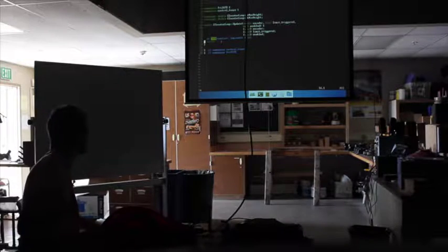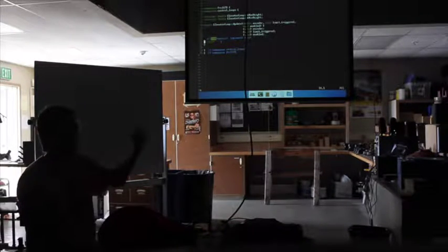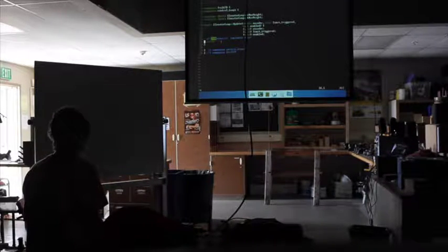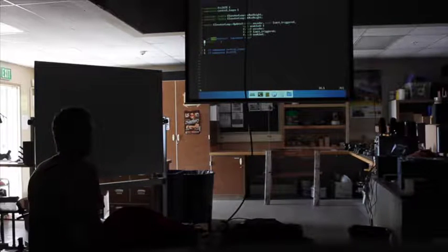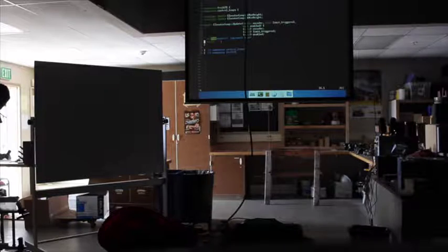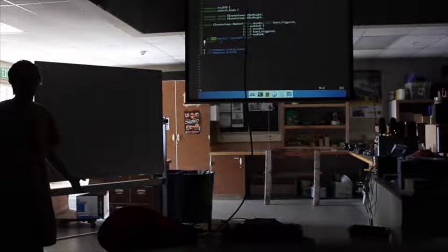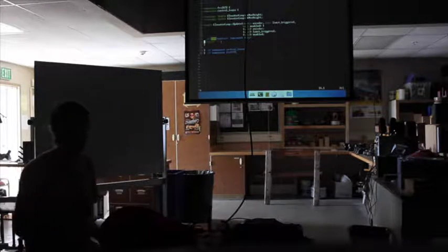So we should start writing out some of those pieces. If we want to track our status for zeroing, what's a way to do that? This function iterates, right? So we can't have any blocking calls in it. We can use a state machine. So we have a couple different modes our system can be in. It could be an unzeroed mode. It could be in kind of a zeroing mode. So we're going to start, we need to reset everything. And then we're going to slowly want to travel down. And then once we're zeroed, then we can just let the system perform, right? Does that make sense? Okay, so how can we implement that here?